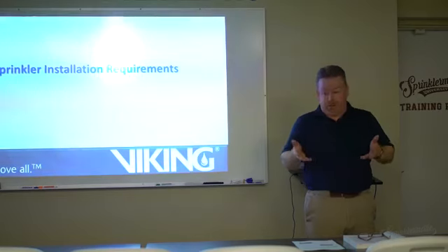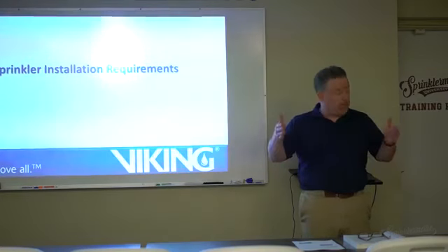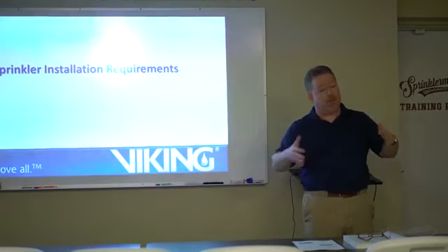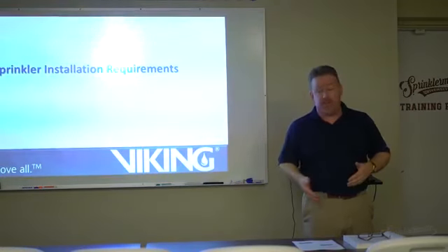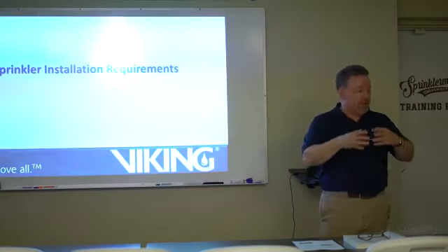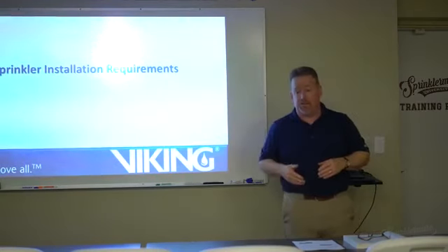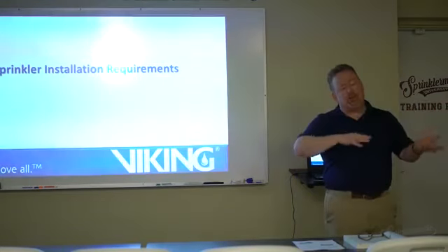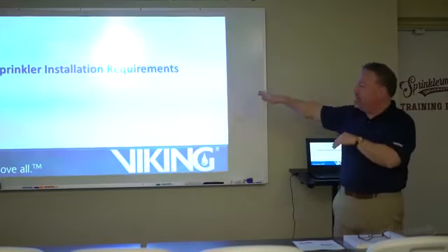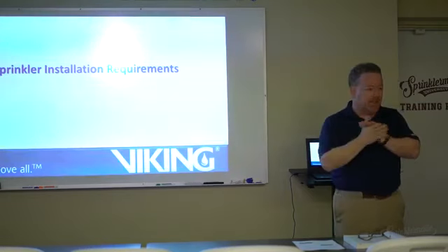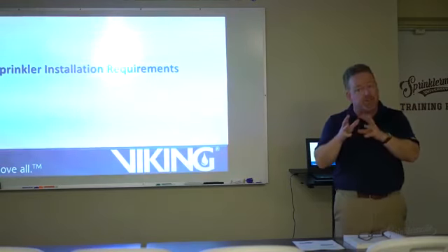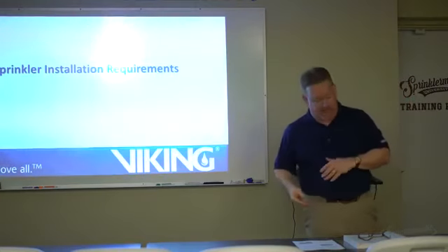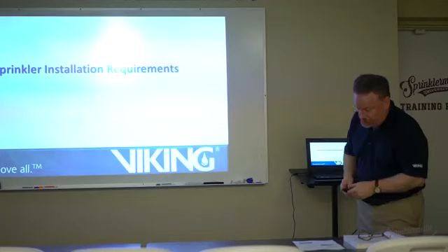So that's a critical point in the whole decision-making process. Once you've decided to use light hazard occupancy, you're limited to this particular family of sprinklers. We're also going to see, as we get into some of the other design criteria, that once we decide on a hazard classification, it may have an impact on some of our other decisions as well.